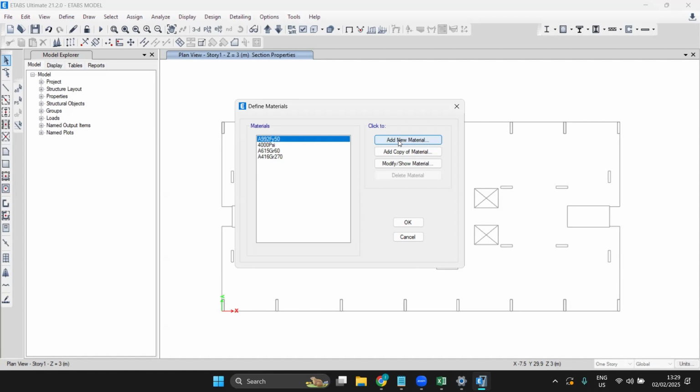So what is the dimension? Let's say 3 meters, right? So wherever you open, when extracting the DXF from the basement, try to keep the same origin point from 3 meters. Then delete this, you don't need this. Keep it in any layer. Even if you want to create a new layer, create a new layer, or if you want to use the same layer, use the same layer.